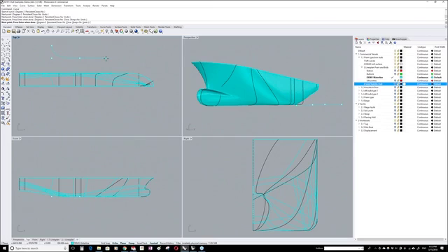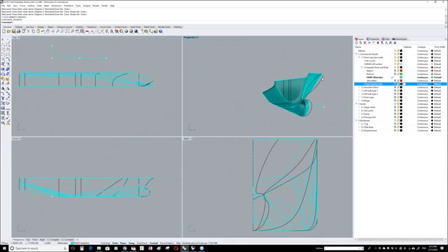Here we have a curve, and the control point here. I will first finish the curve and put the control points on. This control point is not on the curve as well. And it's exactly the same with the curves of the surface. They're not on. Only when it's the end of the surface, like here, this control point and that control point there is on the line, the end curves are on the surface.